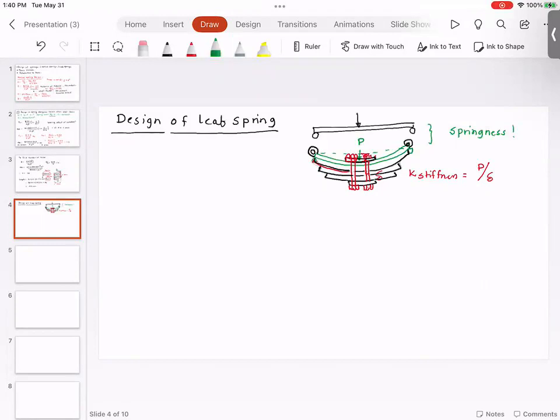And then there will be a support that will be mounted or attached to the axle. So in other words, the vehicle, and I'm not showing the tire, but the wheel could be somewhere here. So that is how the leaf spring will be attached. Now you will have something called the full length leaf.